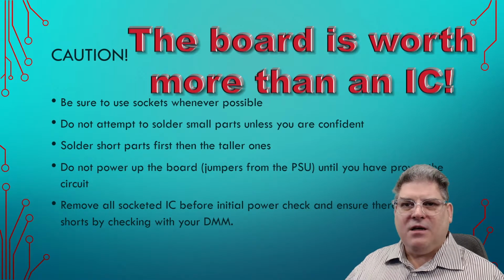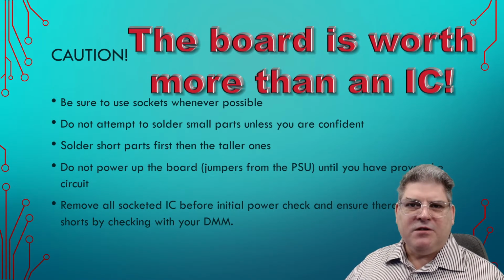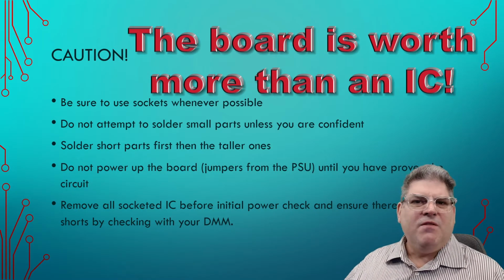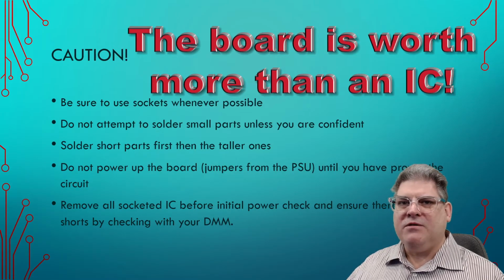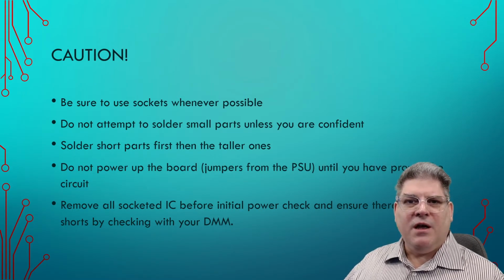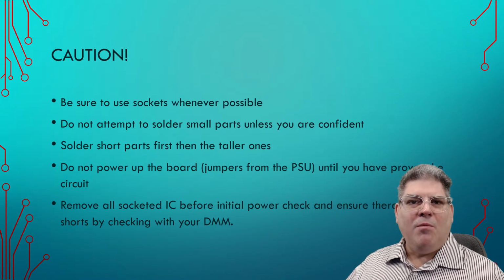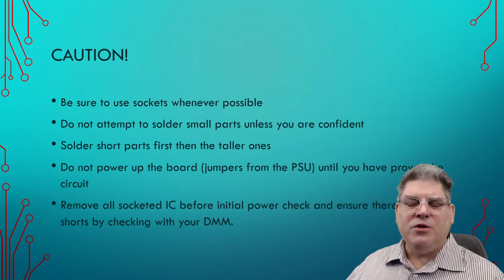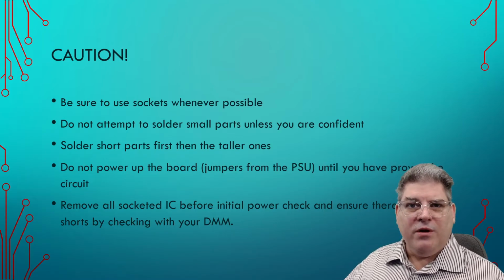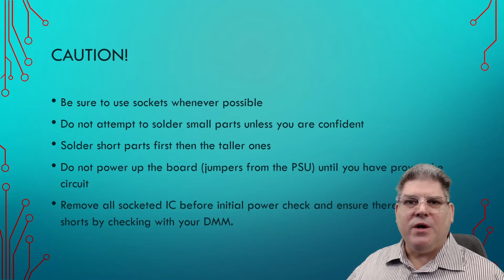That's for inexpensive parts like a 7400 series, or even a microprocessor. I might decide to cut the pins off that and remove them as well, just as a time savings. But if it was an irreplaceable ROM on your Lisa 2 computer that you're trying to restore, you're absolutely not going to do that. So one of the reasons back in the day that they would socket all of those PROM chips was so that they could actually remove them.